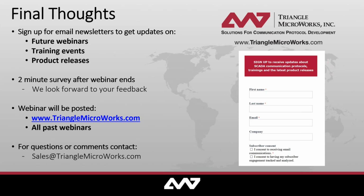Now, you can certainly also do this in other contexts. If you're configuring a gateway, for example, and you need a data model for your server, that's another instance where you would create and modify the capabilities of a device. But if you just purchase a device off the shelf as a system integrator or utility, you can't necessarily just open up that file, add functionality by editing the SCL file, save it and push it back down, if that particular device doesn't support it. Christoph, if you have anything that you'd like to add, go ahead. I think the answer was fine.